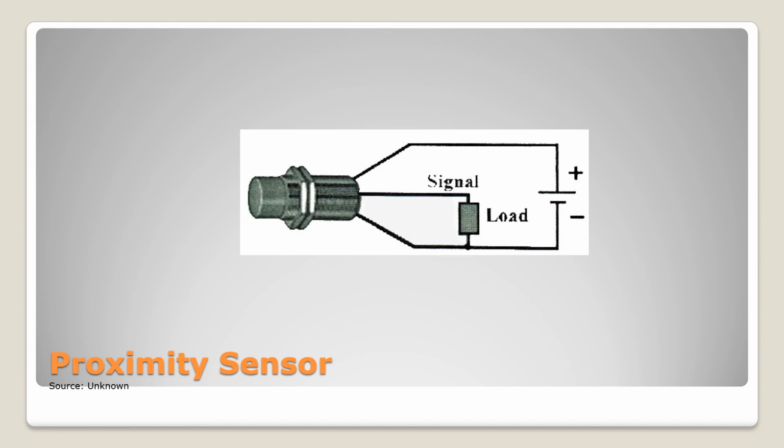So if you had, as an example, a metal Coke can moving down a filling line, you would want to be sure that you are actually putting product in the can, not on the floor. So this device could determine that the can was directly in front of the fill nozzle and would then dispense the product. The thing about this is, you see, it has no physical contacts. It's going to operate purely electronically with no moving parts.